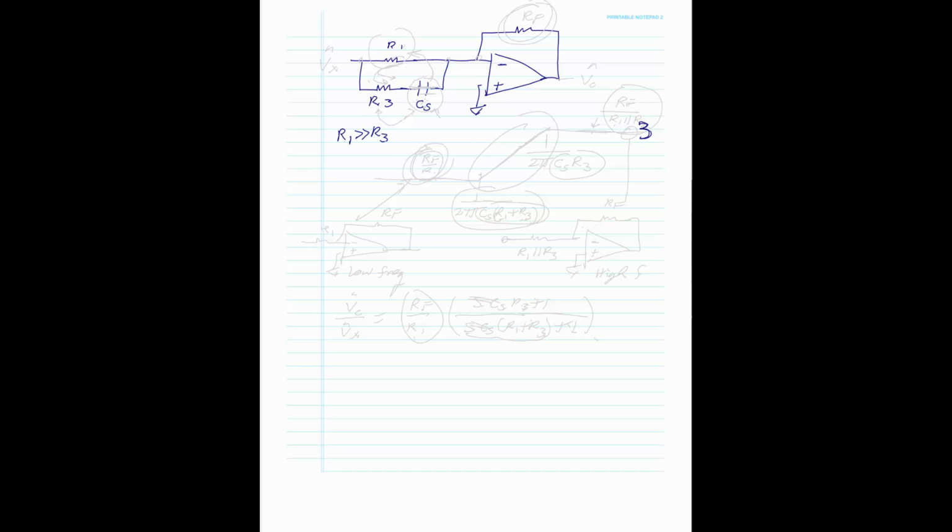And now we have RF, and we have again Vx hat and Vc hat. Looking at the transfer function, again, I don't need to derive all this. I can see what's happening. You draw it. What happens at low frequency? You have this over this because the capacitor is open.